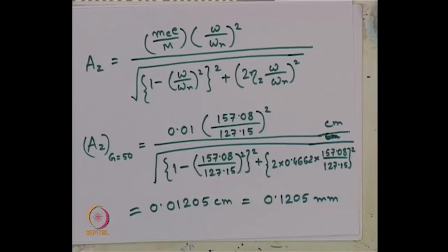You can do a cross check actually, you can take any problem, take the load same for both constant force type and rotating mass type, you will see that at operating frequency their displacement amplitude is exactly the same.